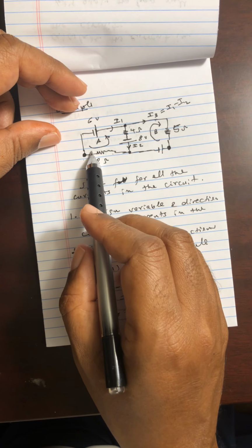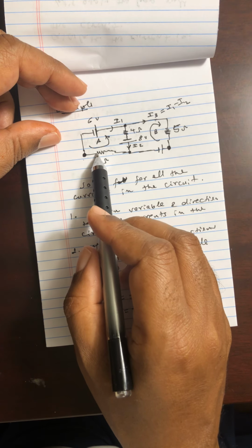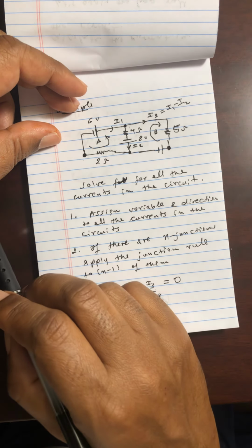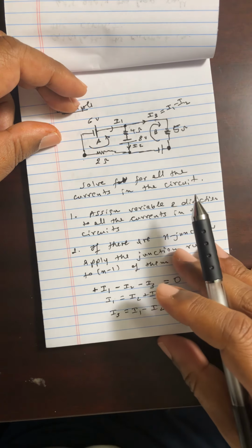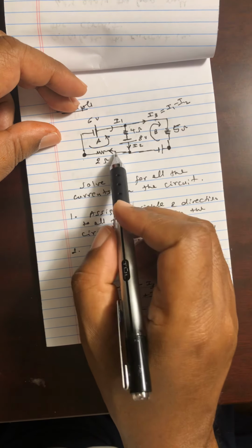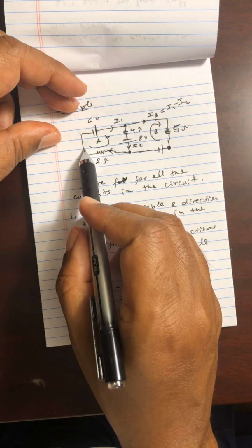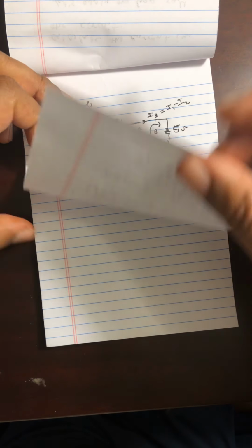But we're crossing it opposite to the direction of the current. So the potential difference across this resistor is going to be positive, okay? And so that is resistance 2 times the current I1, and it's going to be positive because it's being traversed opposite to the direction of the current. The current is going this way, but we're traversing it this way, okay? So the first term is going to be 2I1,